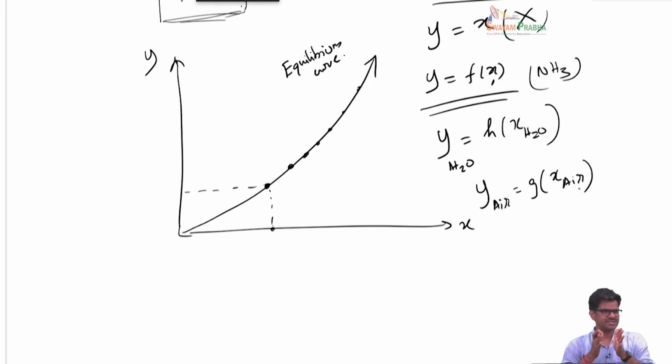So, for the same system, there is a set of equilibrium relationships, but generally we do not deal with the insoluble components. In this case, air is not so soluble in water, and water is not going to evaporate too much into air. So, we are not going to consider these compounds. We are going to look at only the more soluble compound in this case, which is ammonia.